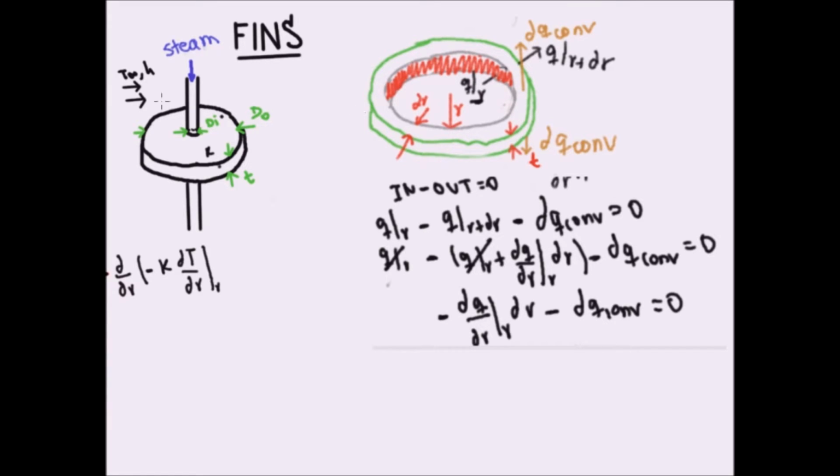So how do we express that area? Well, I always like to think about just an extended horizontal wall. So we can actually unroll this inner surface, this inner circle, and imagine extending a horizontal wall. And then what would the length of this wall be? It would exactly be the circumference of this inner radius, which is 2 pi r, right? Because it's evaluated at r. And then what is the height of the wall? The height of the wall is this thickness element, t. So then how do you calculate the area of the wall? It's just the product of its sides, and then the area would just be 2 pi r times t. So that's the area element.